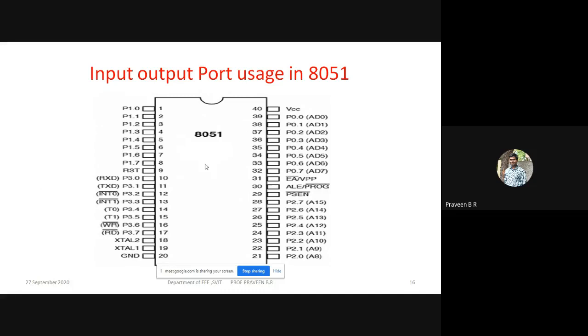The ninth pin is called the reset pin, which resets the microcontroller after the operation. From the 10th pin to the 17th pin, they are used for port 3.